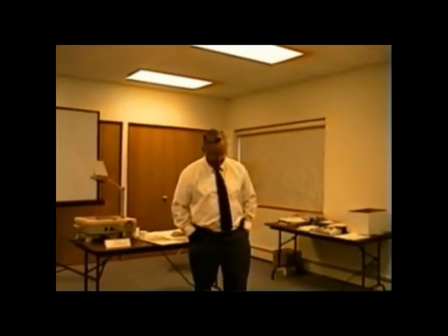Absolutely. And see, Jeff is saying for the temperature rise it's good, and I know exactly what he's talking about. So let's talk about that. Let's go back and ask that question. In other words, we have a 50-degree temperature rise, and specification was 45 to 75. That means that that furnace is working at the lower end of the temperature rise, okay? But it's working perfect, and it'll last forever. All that needs to be done to the furnace is do a PM check every year, clean it, make sure everything is proper, and it'll just work. So, is it good for the furnace? Yes. Is it good for the customer? Yes. Oh yeah? Let's talk about that.